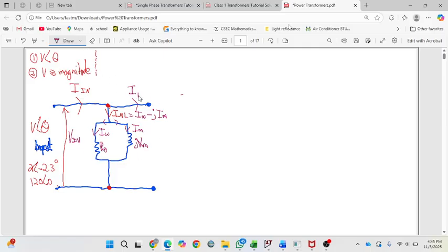So when you're inside the transformer now, you have a different set of losses. When you reach here now, you have another resistor and another inductor, and then you have your coil, and this coil goes back to here. So far in the circuit, we have this I1 current, which is basically your input current minus your small no load current here.